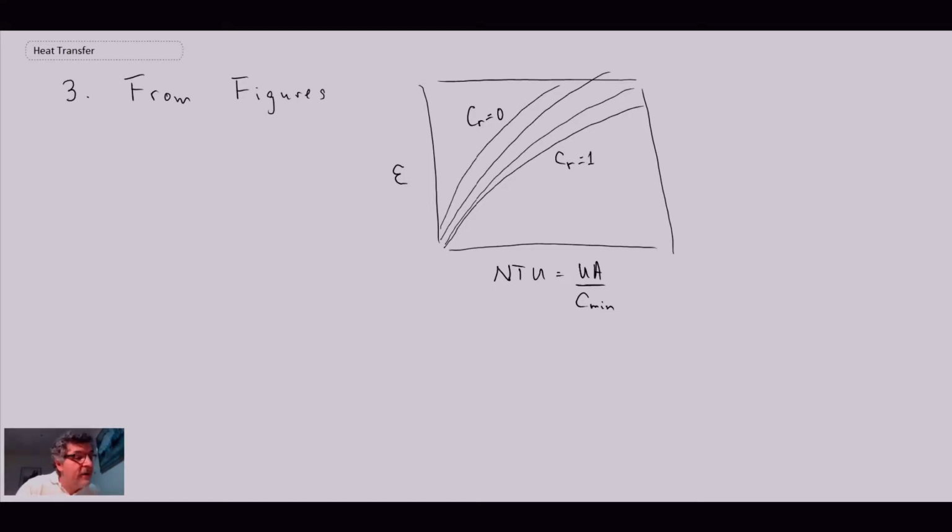Now what you would do is take the values. We said CR was 0.9408 and NTU was 1.59. So you go onto the plot, let me do red so that you can see it a little better. You find the location, you work your way up, and 0.9408 is going to be pretty close there. You then go across and read the value of epsilon, or the effectiveness, and from that you get 0.59. So we get effectiveness of 0.59 by reading a chart.